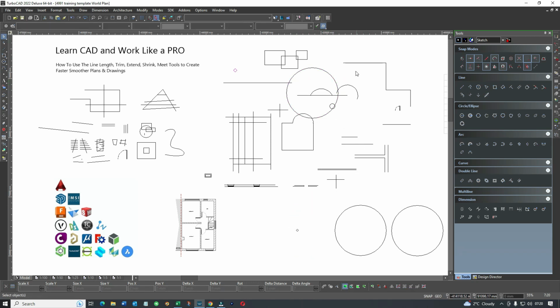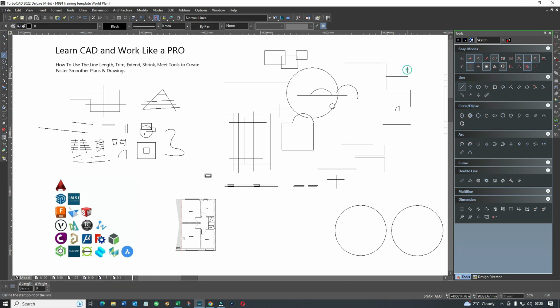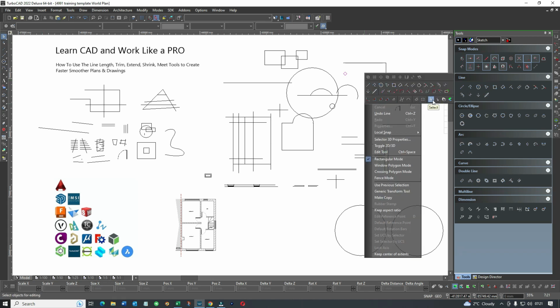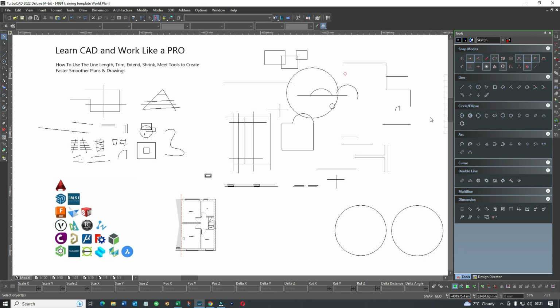So we'll do it one more time just to make sure you got it. Changing from whatever position you're in, be it the line tools, and you want to grab something, instead of going up and hitting this and getting the select tool, just hit spacebar. So spacebar changes to the select tool. So in other words, switch to the select tool using spacebar. That's the shortcut. It's a brilliant little shortcut, and in fact it says it. If I hover over the select, it says space, and I didn't pick up on that for quite a while. Well, there you go. So use the spacebar to switch to select, much quicker than going up or invoking the right click and then picking up on it within that pop-up. Right, next one, which again I consider a really important one.